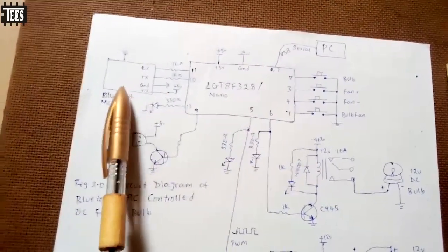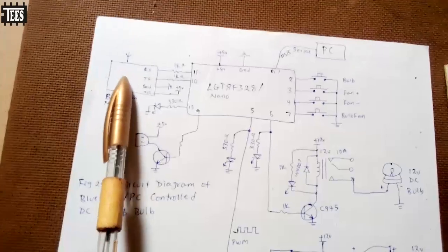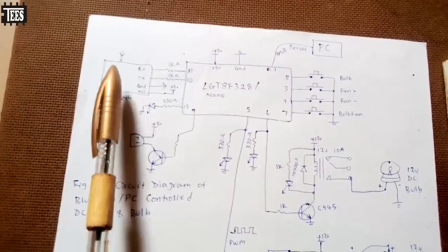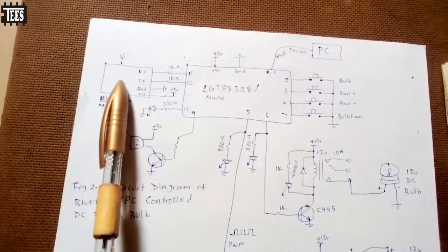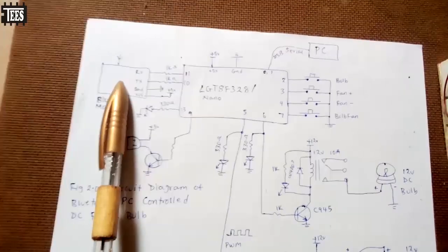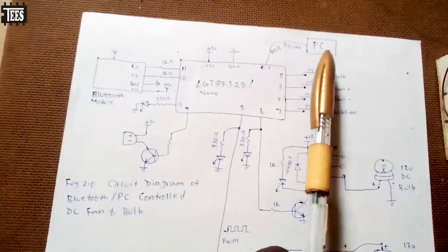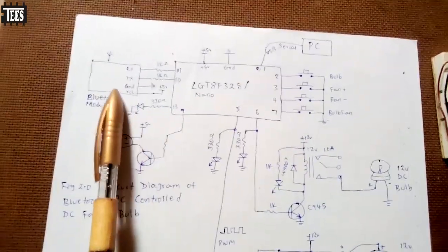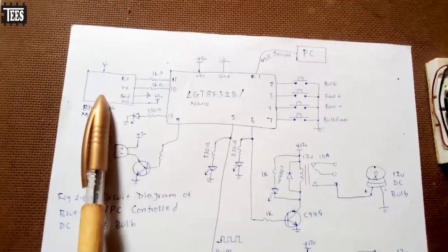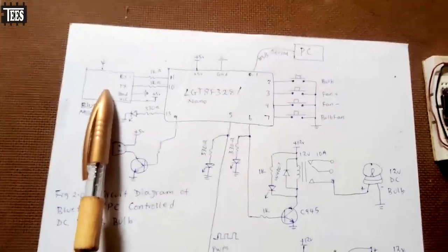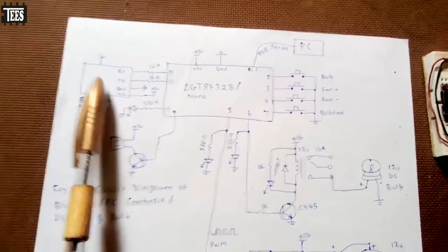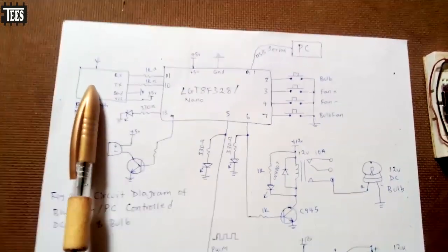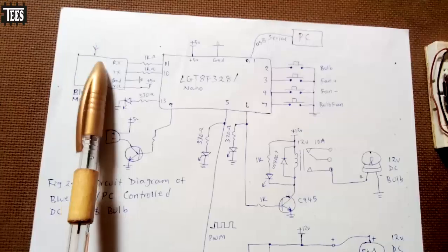Then from our Android phone, via Bluetooth communication, we can issue commands via a serial terminal program. Our Arduino IDE on our computer already has a serial terminal program. Our Android phone doesn't come with a serial terminal program, so what you do is just go to Play Store and download the Bluetooth serial port app. When you download that, you can be able to do it.